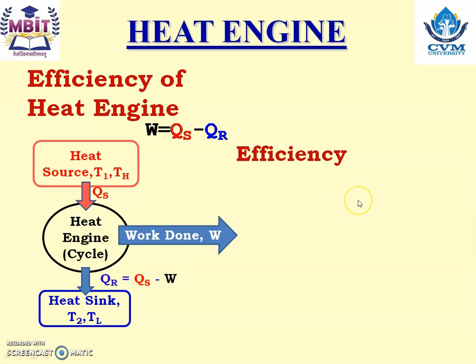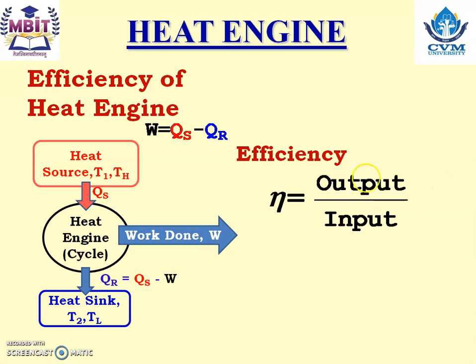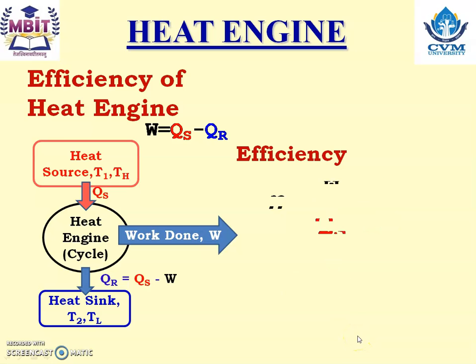Now the efficiency of a heat engine. How do we calculate the efficiency of a heat engine or anything? Yes, the equation is output upon input. Now what is the output in the case of the heat engine cycle? It is work done. And what is the input to the heat engine cycle? Only QS. So work done divided by QS is the equation for the efficiency.